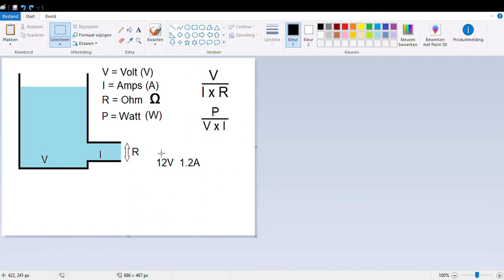With regards to the device I've shown you, the appliance, it required 12 volts, 1.2 amps. But the thing is, I picked out a 12 volt 2 amps adapter. But that's not a concern because it still will draw 1.2 amps. Why? Because the voltage is fixed. The adapter will deliver 12 volts. It's not going to change it because you connect a light bulb or you connect a cable router. It's not going to change the voltage. These devices work on 12 volts.